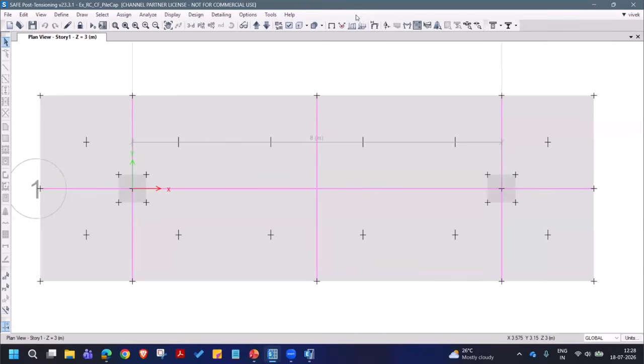Yes, there is one pertinent question, that is punching shear check for shear walls. Punching check is for a single joint, which is a column location. For wall locations, it is not performed. The reason is that there are several joints lying along the length of the wall, even if it's a single planar wall or a multi-legged wall core, then the punching perimeters will overlap, right? So such a condition and the design procedure both are not available for the design to implement in the program.